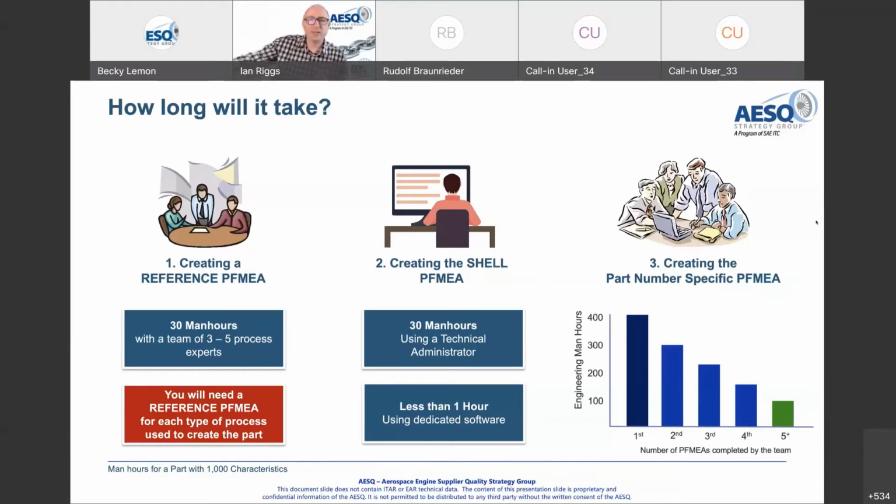We need to invest in maybe air detect, or some mistake proofing to make sure that the part is going to be held securely, etc. Once you've done the FMEA and it's too late, you've already spent your money, it's going to be very difficult to convince your organization to go and invest in new fixtures, new tooling, etc.